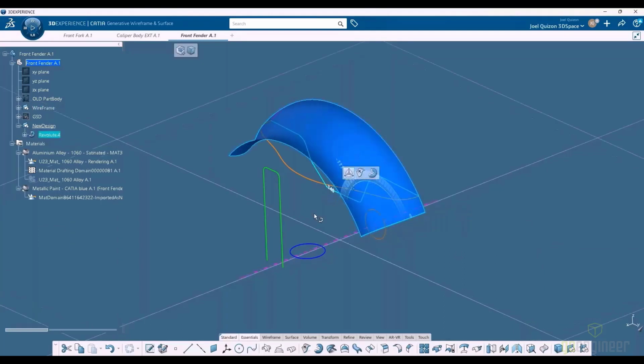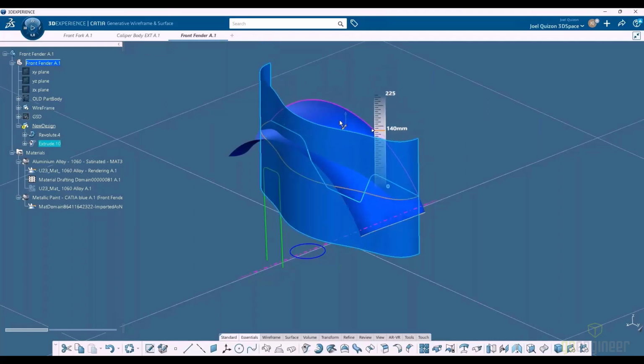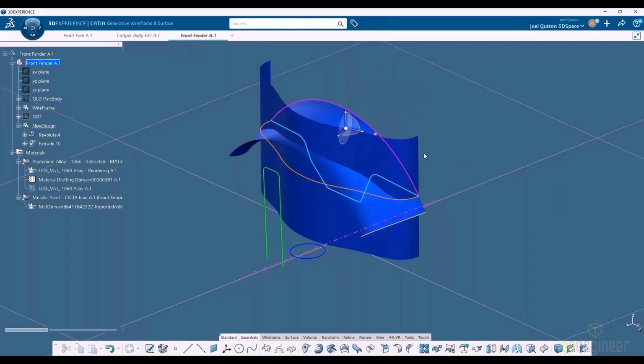There it is. So just grab that and move it over. I'm going to take this one and just extrude it. So just doing an extrude. Now I'm holding my control key to do an extrude midplane. So that was just a quick control key to extrude it based via your midplane.